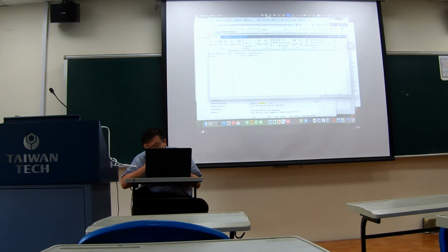So in fmincon, if you read an external file, you only allow a single variable x. So right here, x1 has to be x bracket 1. x2 becomes x bracket 2. And then return the function value y.